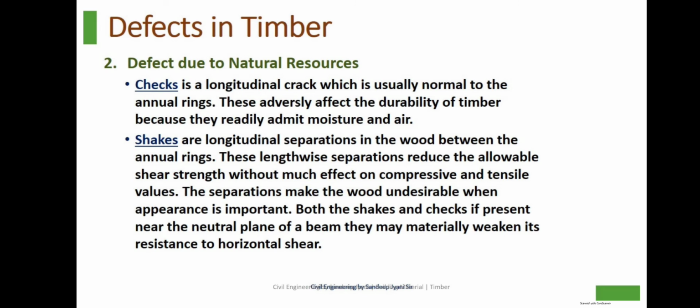Defects due to natural causes. Checks: a check is a longitudinal crack which is usually normal to the annual rings. This adversely affects the durability of timber because checks readily admit moisture and air. Shakes are longitudinal separations in the wood between the annual rings. This lengthwise separation reduces the allowable shear strength without much effect on compressive and tensile values.